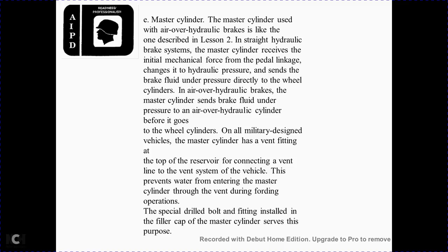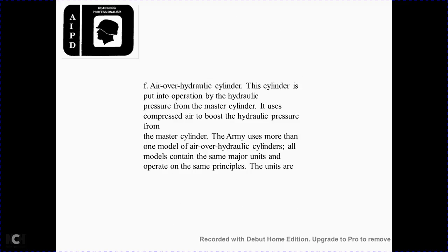On military design vehicles, the vent fitting on the top of the master cylinder reservoir is connected to the venting line with the venting system of the vehicle. This prevents water from entering the master cylinder through the venting during fording operation. A special drilled bolt fitting is installed with the filler cap of the master cylinder for this purpose.